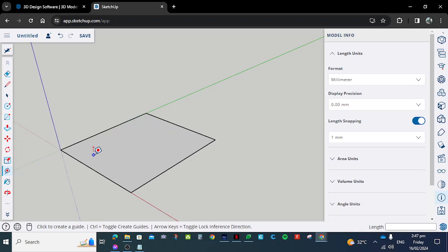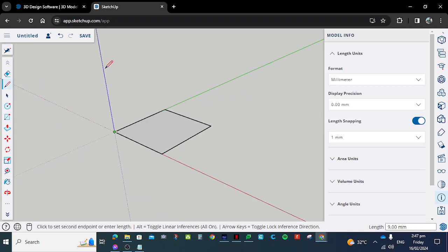making a cube. So we can actually do it this way. That's from this point to that point is 10. So I'll just type 10, 1 and 0, and then I'll press escape. I'll just do the same thing here again. From that point to that point, that would be 10, and I'll do the same here.